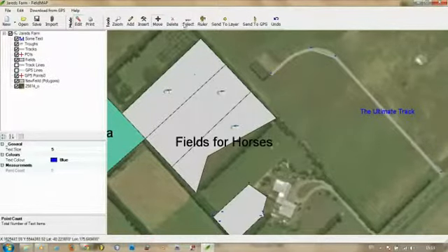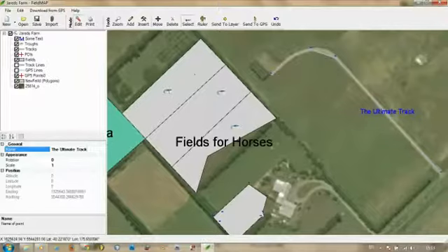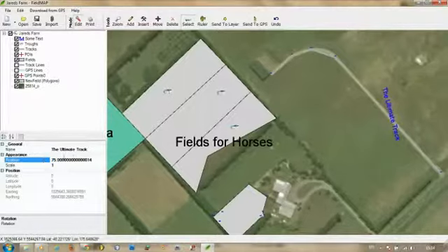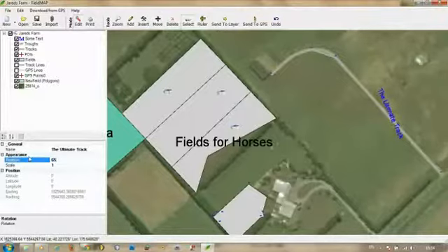To rotate or scale text, use the Select tool to click on the text or its parent field. You will see in the Properties menu a section labelled Appearance. Underneath, you will see Scale and Rotation. Scale can be set to a value between 0 and 1, and rotation -360 to 360. Play off these values until the orientation of your text is satisfactory.